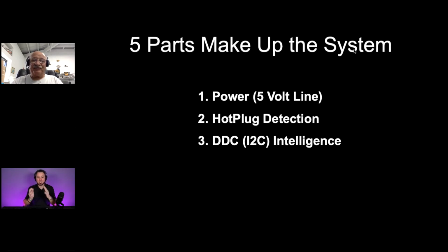But that is especially true here, because if you don't have that cable seated just perfectly, that pin's recessed, and your number one problem shows its face: no power. And they recessed that on purpose because they wanted to make sure all the data lines were hooked up before power starts. Yeah, right. It was a good idea, it's just that some people don't stick it in all the way.